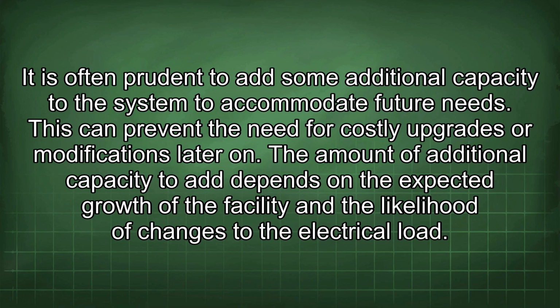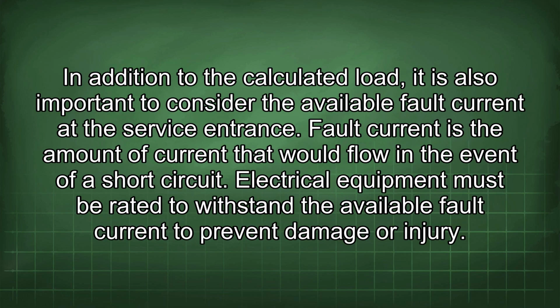In addition to the calculated load, it is also important to consider the available fault current at the service entrance. Fault current is the amount of current that would flow in the event of a short circuit. Electrical equipment must be rated to withstand the available fault current to prevent damage or injury.